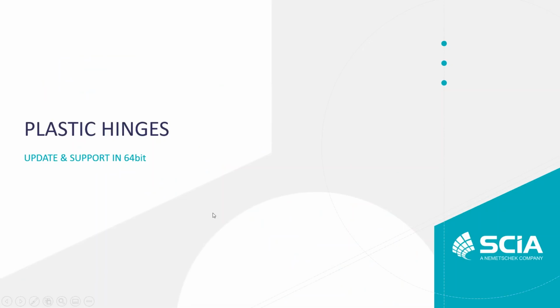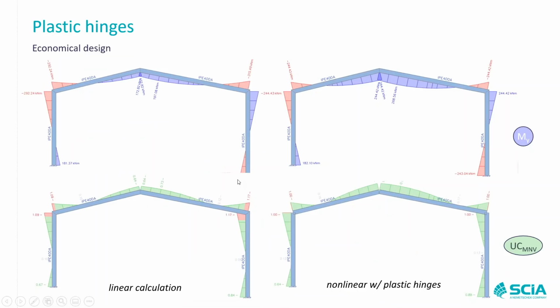Then another topic, I will not show it live, I will just shortly mention it: plastic hinges. First of all, because it's not a very popular feature in SCIA Engineer and not many clients use it, I want to explain where it is used. Here you see a comparison of two different frames calculated in SCIA Engineer, once in a linear calculation and once the same frame but with nonlinear analysis with plastic hinges, without geometrical imperfections and geometrical nonlinearity, just plastic hinges.